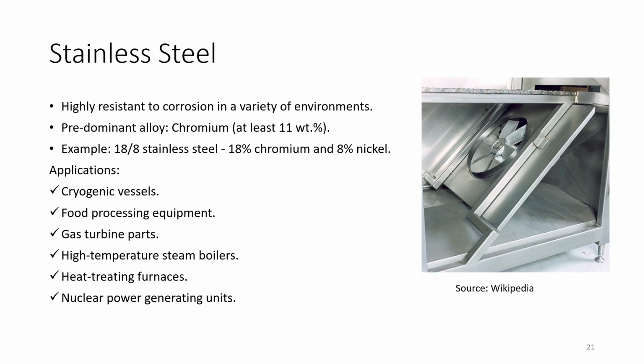Yes, by weight, but 6% is not there. 6.7% is for cementite; if you are taking the cementite composition, you'll have 6.7% carbon and the remaining percent iron. If you are choosing cast iron, then it is between 2.1 and less than 5%. Okay, that means in 100 kilo it is nearly 5 kilo.